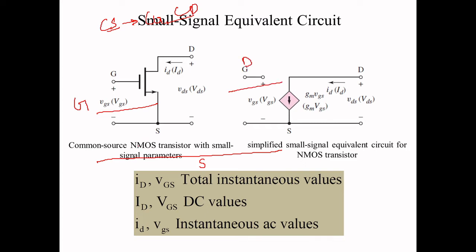Between gate and source, the MOSFET gives a higher input impedance because of its structure: oxide is present below the metal, as we already covered. You have a metal, an oxide, and a substrate, with the inversion layer channel, the source here and the drain here. The oxide is a dielectric material, so it does not allow electrons to propagate.